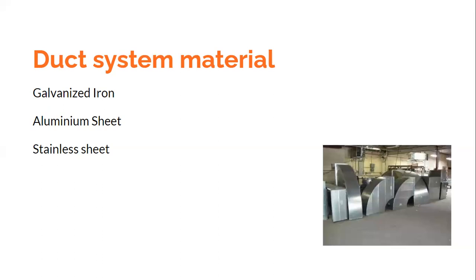And what higher pressures did we talk about? We talked about pressures in the range of 3.75 and above. In the medium range, it is 3.75 to 6.75 inches of water column, water gauge, and in the higher pressure range, it is 6.75 to 12.25 inches of water gauge.